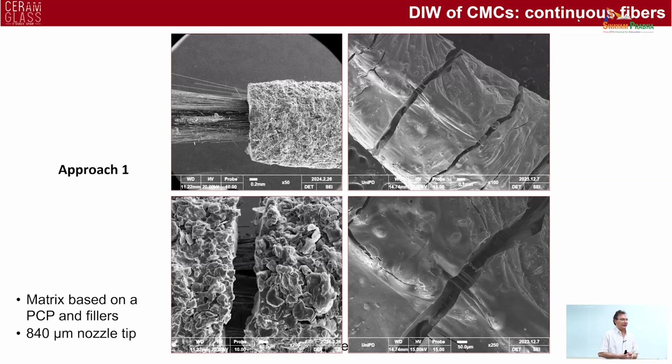And typically, if you want to have a crack-free component, you have to do this up to 10 times, which is what people do because they don't have any other choice, but it's not really ideal. So having a 3D printed cracked part is bad, but it is still acceptable because this is what would happen anyway.